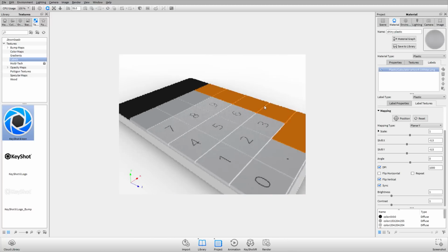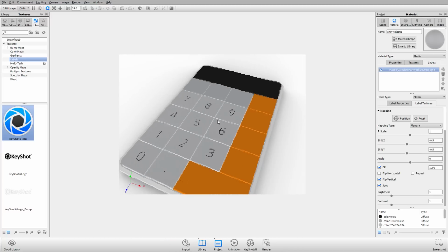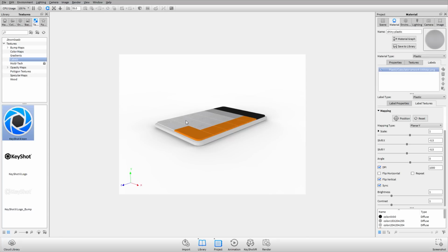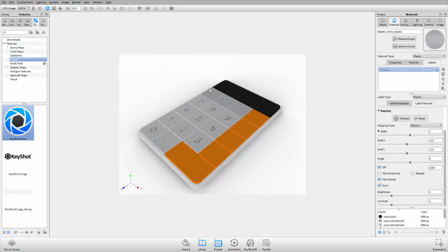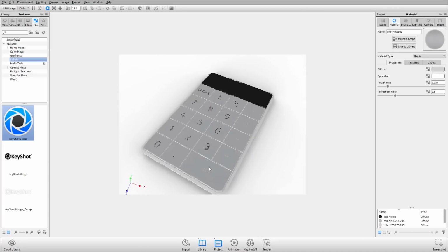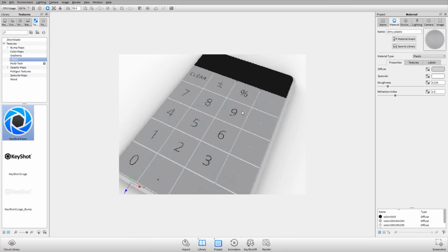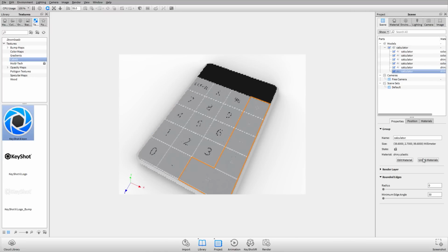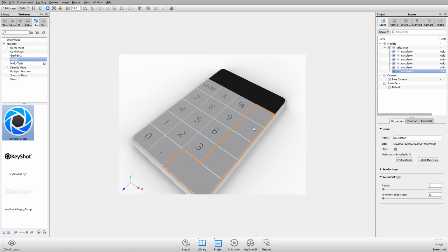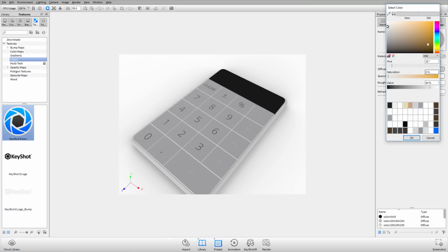So that's a great way of quickly assigning that label. It's going straight down onto my part. It's in the right position, and it's at the perfect scale. If I were to copy this material by holding Shift and clicking, and then Shift and right-clicking to my other parts here, you can see that that label has been perfectly applied to all of those other parts. And that's because it's using one label to define them, and that label was created in the global space.